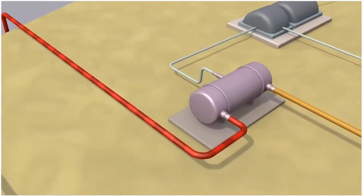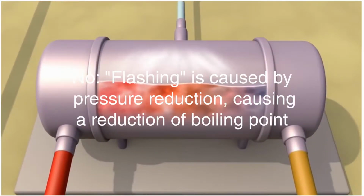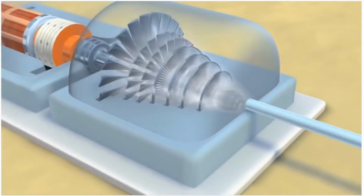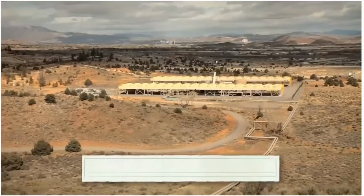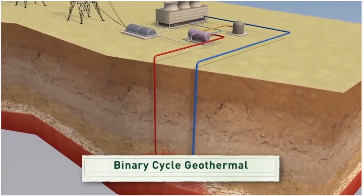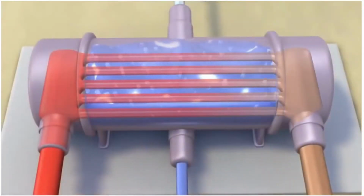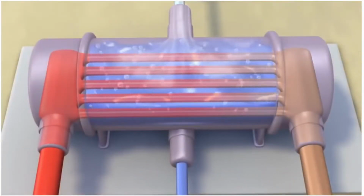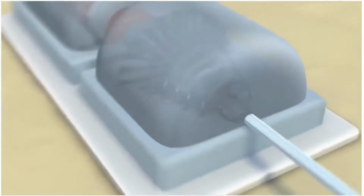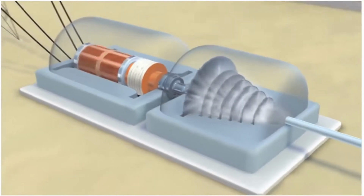Another geothermal technology is called a flash steam power plant. A pump pushes hot fluid into a tank at the surface, where it cools. As it cools, the fluid flashes, or quickly turns into vapor. The vapor then drives a turbine and powers a generator. A binary cycle plant works differently. It uses two types of fluid. Hot fluid from underground heats a second fluid, called a heat transfer fluid, in a giant heat exchanger. The second fluid has a much lower boiling point than the first fluid, and so it flashes into vapor at a lower temperature. When the second fluid flashes, it spins a turbine that drives a generator.